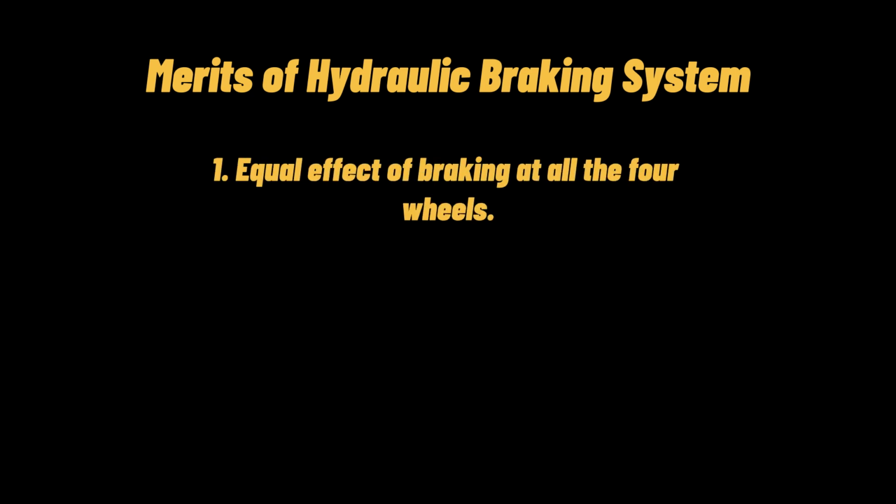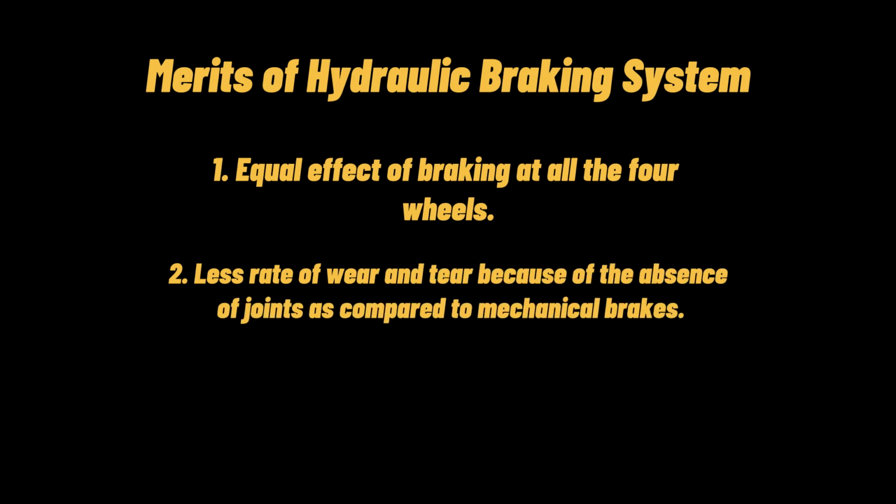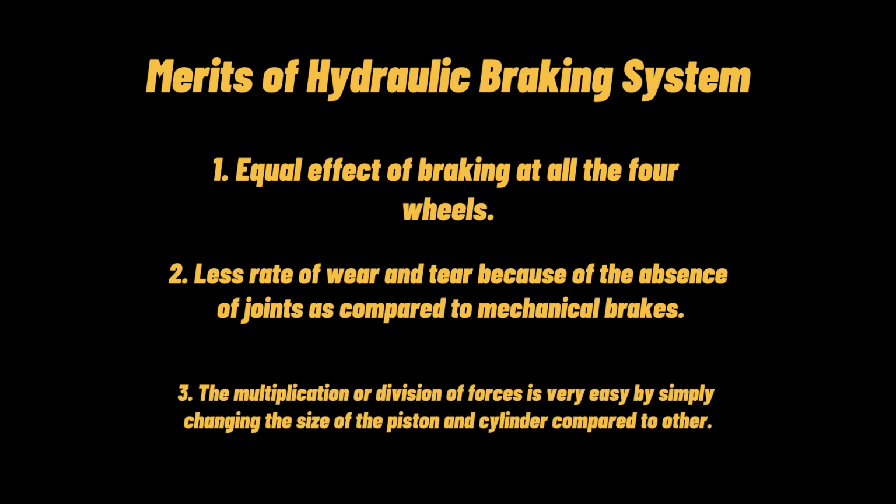Merits of hydraulic braking system. 1. Equal effect of braking at all four wheels. 2. Less wear and tear because of the absence of joints as compared to mechanical brakes. 3. The multiplication or division of forces is very easy by simply changing the size of the piston and cylinder compared to each other.